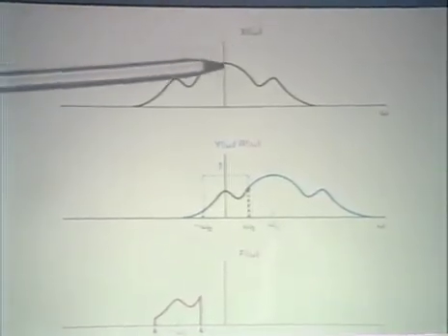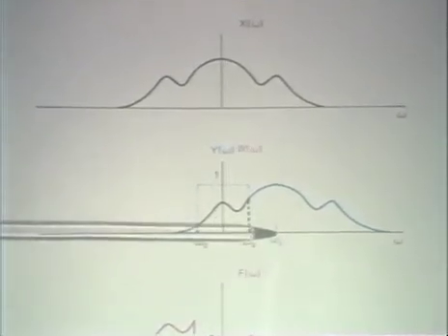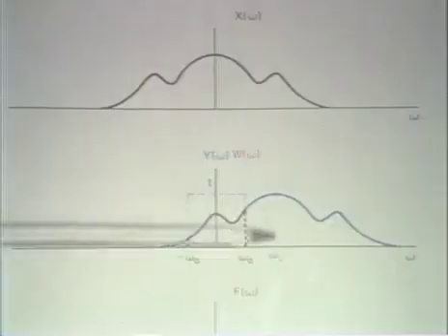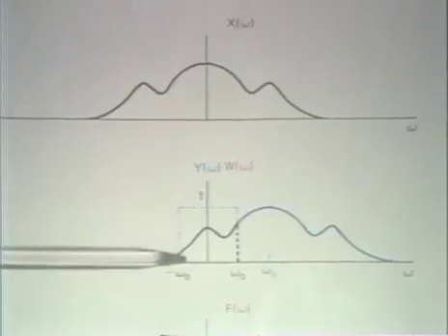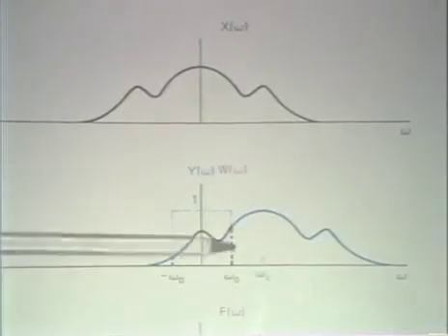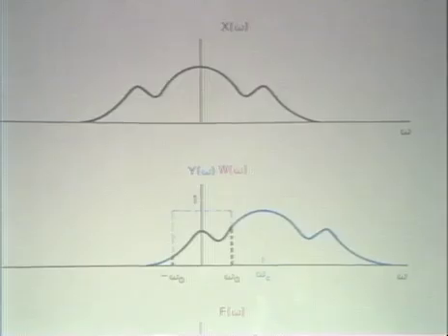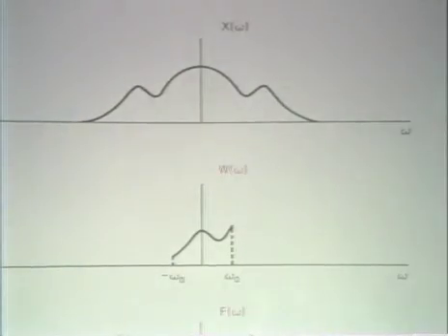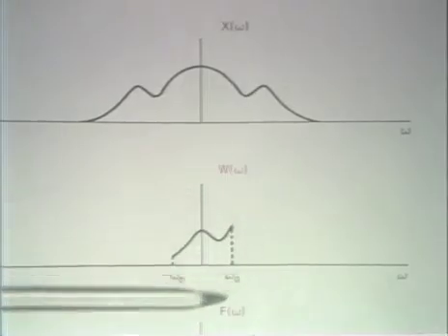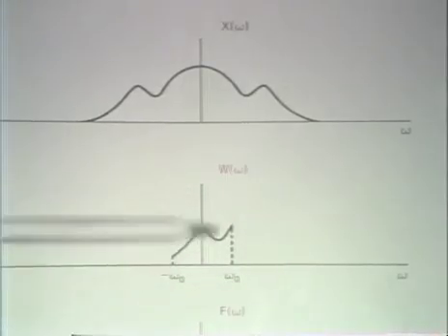After modulating or shifting that spectrum up to a center frequency of omega c, we then have what I indicate here, and the dotted line corresponds to the passband of the low-pass filter. Well, the result of low-pass filtering rejects all the spectrum except the part around low frequencies.